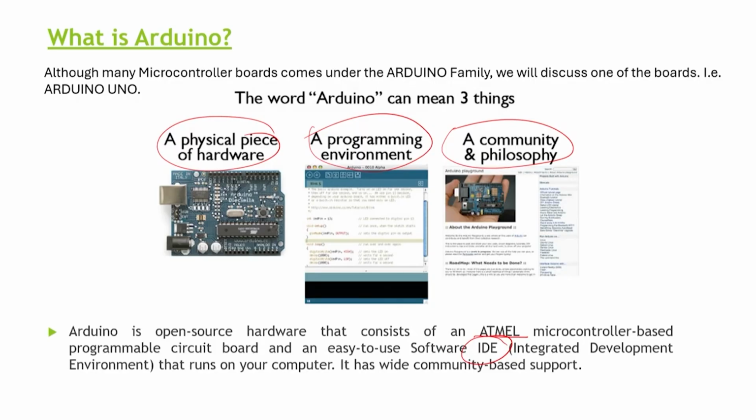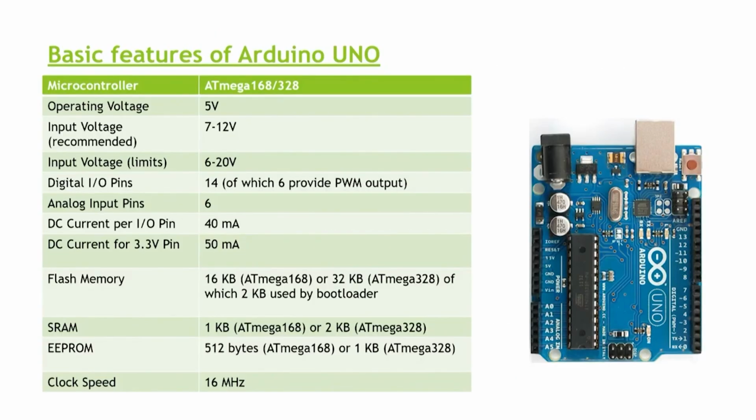These two things together can create very easily some of the simplest Arduinos or microcontrollers. A basic feature of an Arduino Uno is that its operating voltage will be about 5 volts. So, you do not need a very large voltage. Its input voltage can vary between 7 to 12 volts, and it can regulate the input voltage, but we have to take care that the voltage is not higher than this, then it will burn the Arduino.